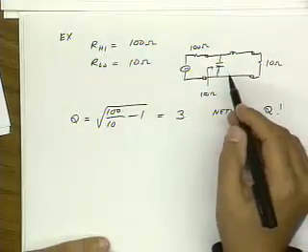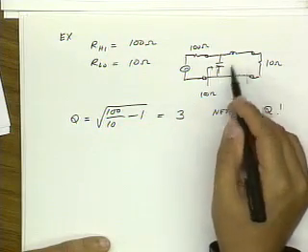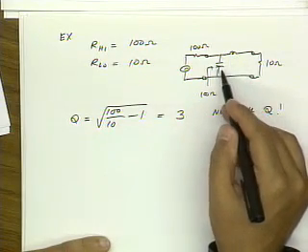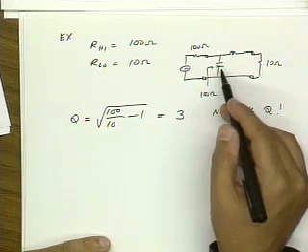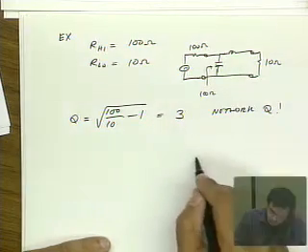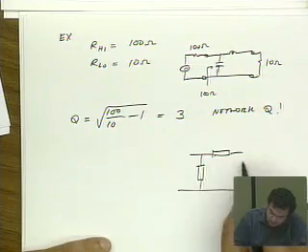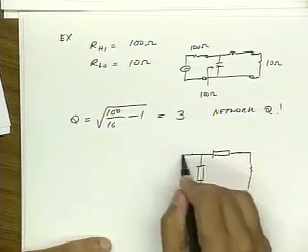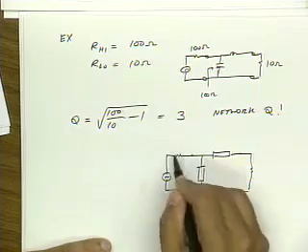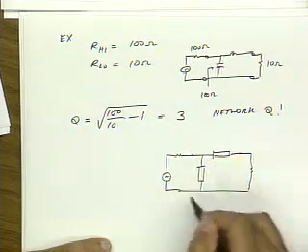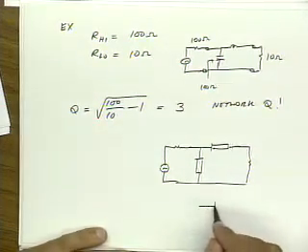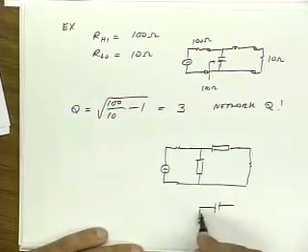The other thing that you might object to is, why did I put the L here and the C here? Is there any reason to do that? Actually, no. This would work for any combination of reactances as long as at the end of the day I can resonate out the resulting reactances. So in fact, I could put a capacitor here and the inductor here.